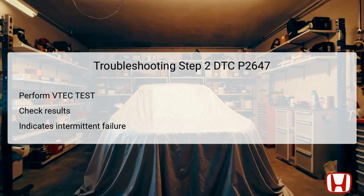If the result indicates P2647, this reinforces the complaint of high voltage in the rocker arm oil pressure switch circuit. If other trouble codes are detected, those codes should be addressed first, prior to revisiting P2647.